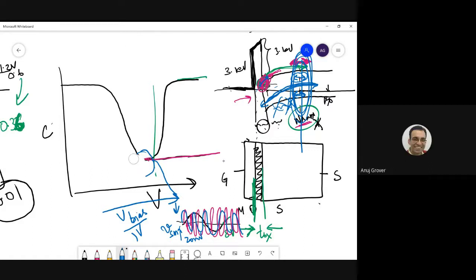In fact, depletion would be somewhere here. Say at depletion, there is no inversion layer, and then I applied the high frequency AC signal. Then will the capacitor undergo any inversion mode or not? Because charges are not able to come. So see, look at it like this. The AC signal is only 20 millivolts up and down. So what will happen to the charge?